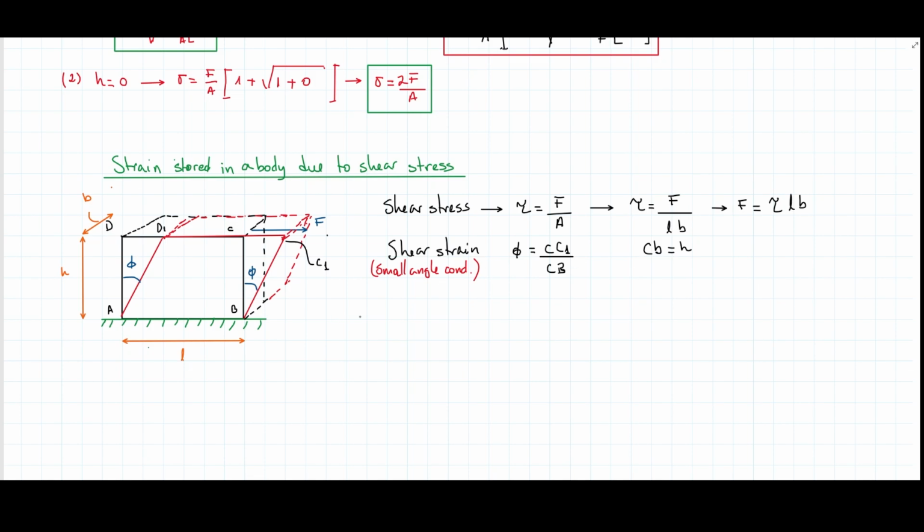Now, if the load is applied gradually, then we know that the work done by the load is going to be represented by an average force, basically, again, P, which is this one here. And then work equals to force times distance. Then the work done, as defined here with these elements we have just found, is going to be the load, F divided by 2, times the distance, but the distance is how much it was extended in the linear direction here, so it's going to be CC1.